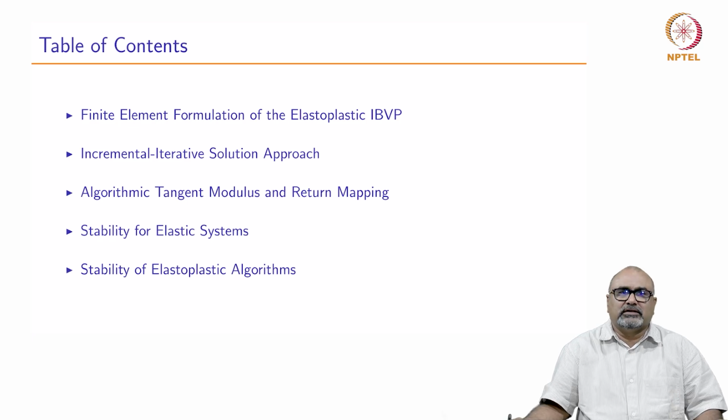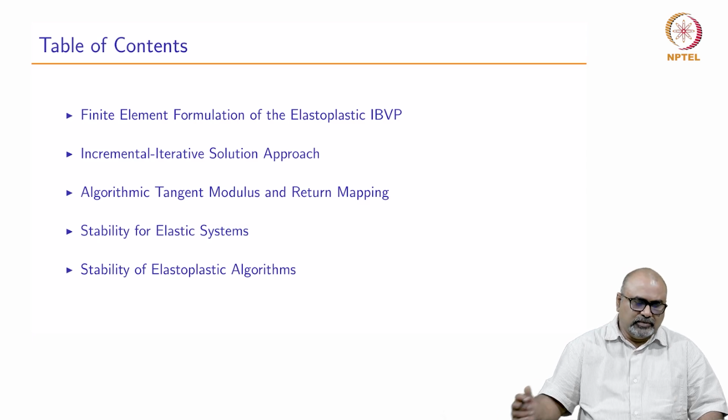We are going to discuss finite element formulation of the elastic plastic boundary value problem. We are going to understand the incremental iterative solution approach. We are going to discuss how to compute the algorithmic tangent modulus and implement the return mapping algorithm. And we are going to discuss stability for elastic systems and stability of elastic plastic algorithms.